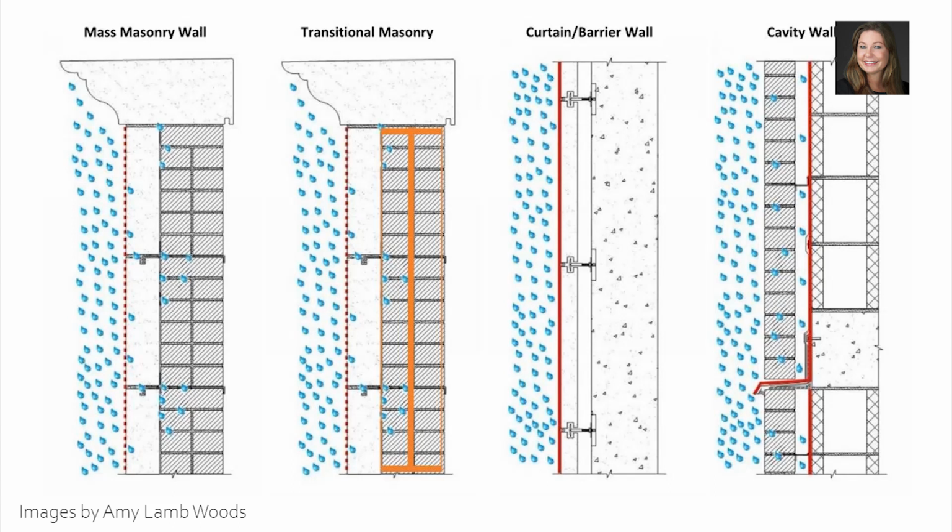Transitional masonry buildings: water gets in, you've lost that thickness, you've lost some of that breathability, and in essence, that steel can corrode. That corrosion is expansive and is then damaging to the masonry materials. So this is one of the most vulnerable types of wall systems out there, and we end up doing a lot of repair and restoration work on these types of walls.